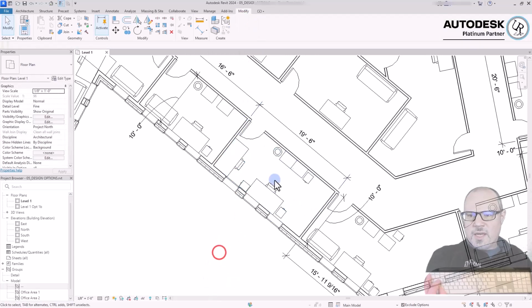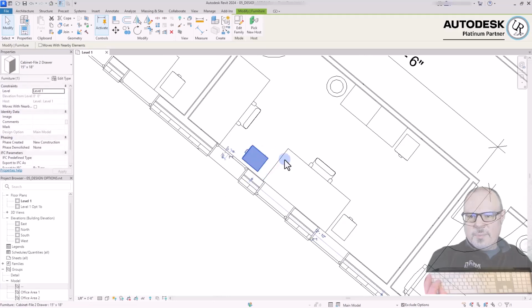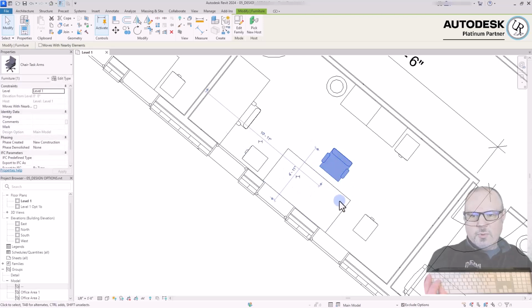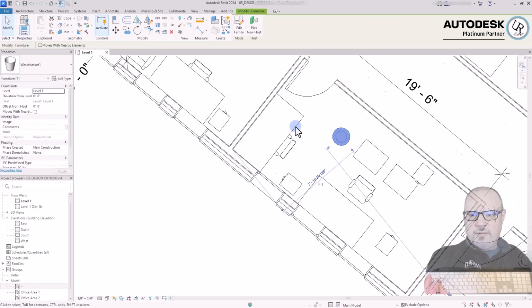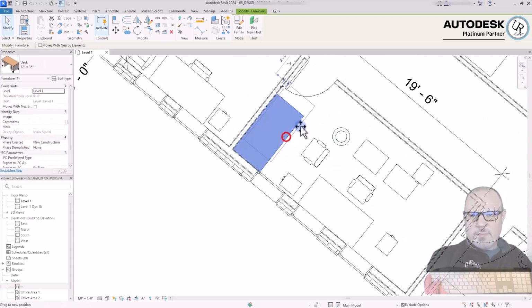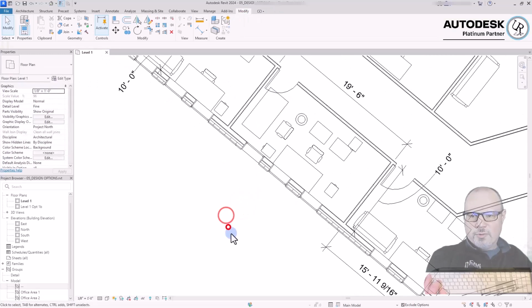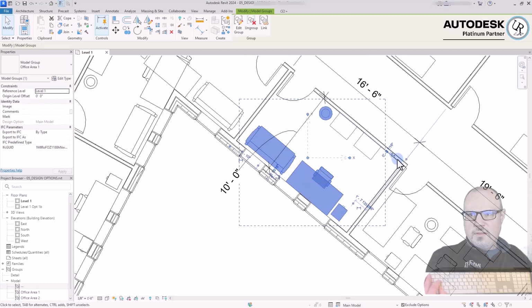Clicking on the group again, another option is to ungroup. You only want to use the ungroup option when you want to make sure that the objects are all independent and can be controlled separately now, because this is not able to be turned back into the same group as it was before, giving me the ability to move and adjust everything from that group as individual objects. So it's basically exploding a block or breaking the group apart, and it cannot be turned back into the same group later.